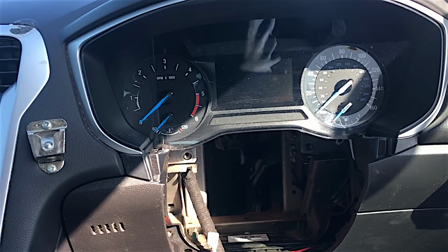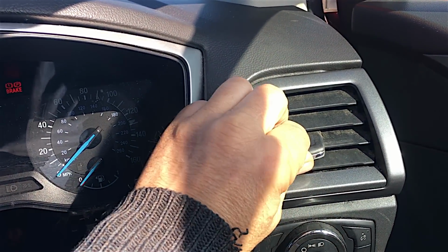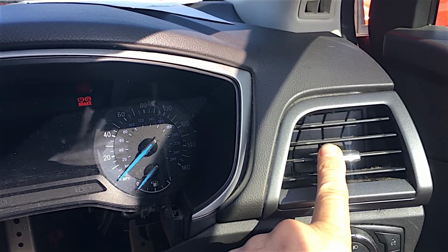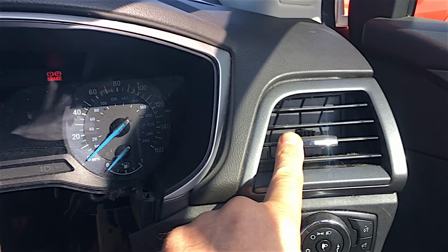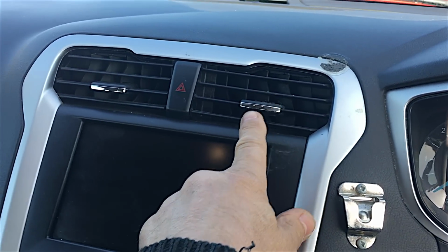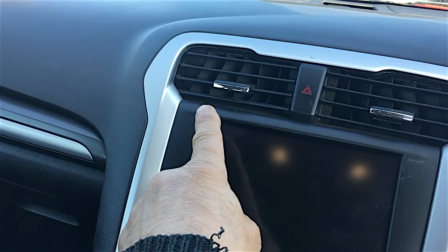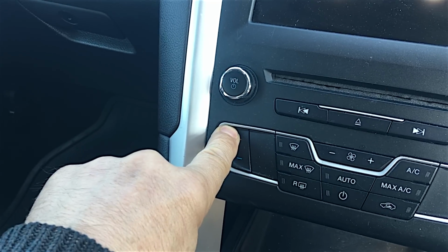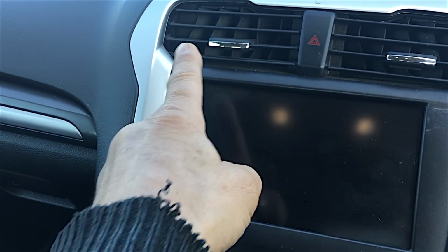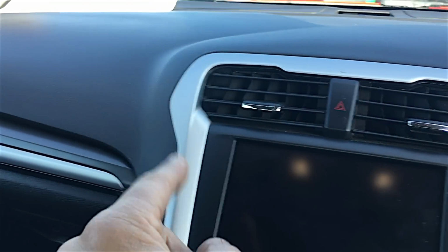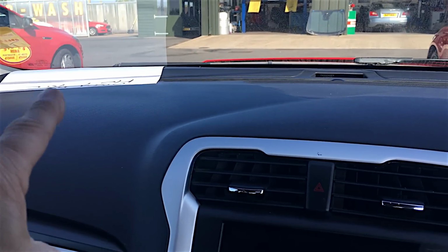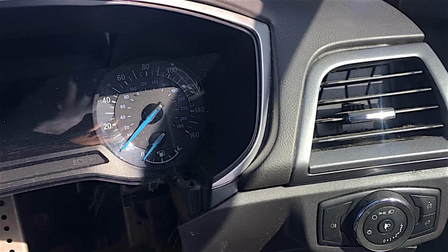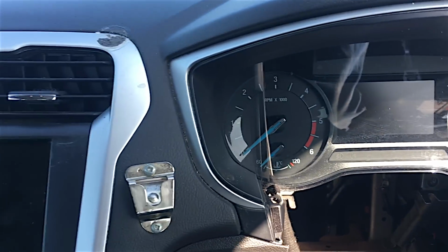On this particular car, the problem is, out of the driver's side, if I put the air to the face vents, I'm getting hot air continually out of the face vents, this one here by the door and this one here in the centre. The passenger side, I'm only getting cold air, and if I use the control here to go from cold to hot and put it fully to hot, it's only getting cold air. So no matter what I do, I cannot get any hot air out of the passenger side air vents or the screen. But this side is hot all the time. I can't make the driver's side cold, which is a bit of a problem.